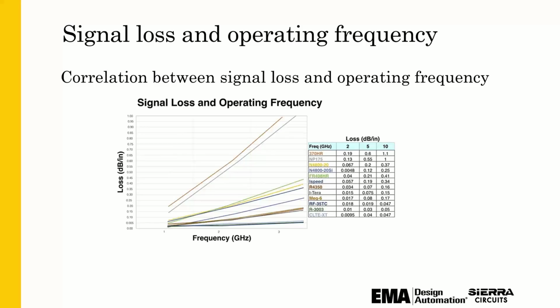So copper loss is also part of the total signal loss, and a little explanation there is due to AC resistance of the signal trace and the applicable return paths. You can have an increase with frequency due to the skin effect. So the copper foil dielectric toothy interface provides an increase of the effective length and thus increases the copper loss. So picking the copper material and the toothiness of the copper material has an important role to play in your total signal loss. So basically use low profile copper foils. And so you can specify that to your manufacturer if that's important in your application.